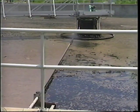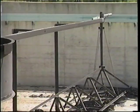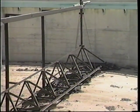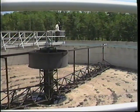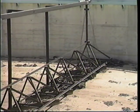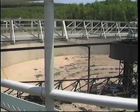Circular clarifiers may have a mechanism that consists of blades or scrapers that move the sludge towards a hopper in the center of the clarifier. The floor of the clarifier is usually sloped towards the center of the clarifier. The unit should be inspected for missing or maladjusted scrapers. The circular clarifier unit usually has a scum collection mechanism as well. Circular clarifiers have an over-torque device that will disengage the unit in the event of a jam or overload.